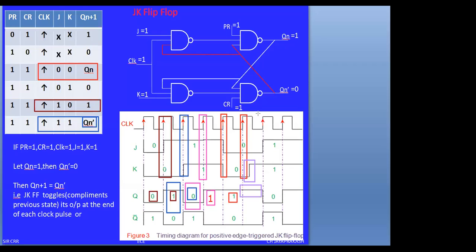Next here, during the fifth clock pulse, sixth clock pulse, again we have got one more trigger. Clock is triggered during this interval of time. Again, both J and K are 1. Therefore, we can see the last condition. When J equals 1, K equals 1, next state will be complement of the present state. That is toggle state. That is 0. And this state is continued again. The same one is applied here. Again, the 0 will be modified to logic 1. Okay. This is with respect to the waveform.